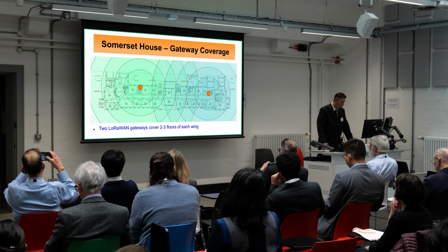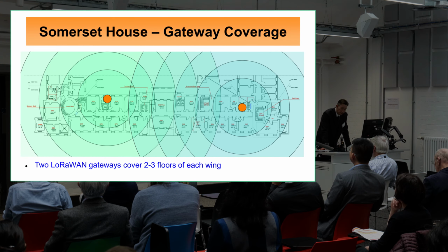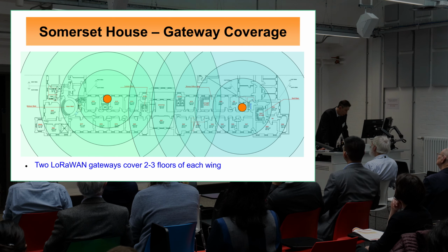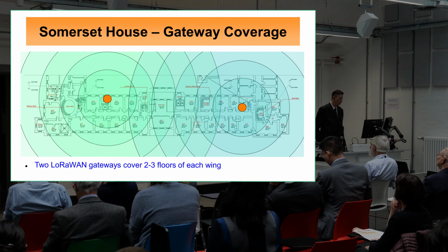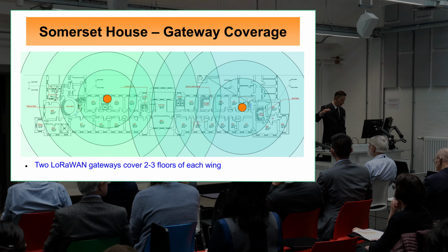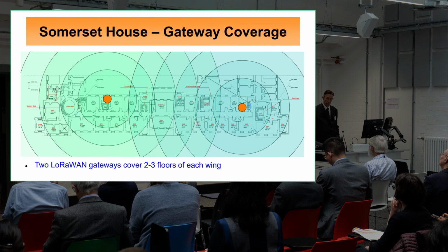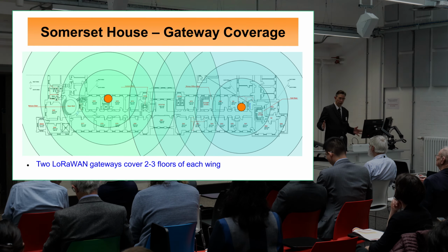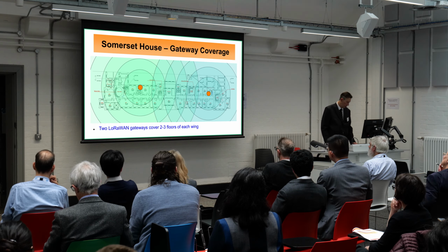And this is an example of actual wireless coverage. So the orange dots are 2 wireless access points. And the floor plan there is of one of the wings. So with 2 access points, not only did we successfully get coverage of the entire wing, but also the floor below and above this floor. So overall, over those 3 wings, we only had 18 wireless access points covering 1,200 wireless devices. So infrastructure cost-wise, very, very small compared to the total amount of field controls.